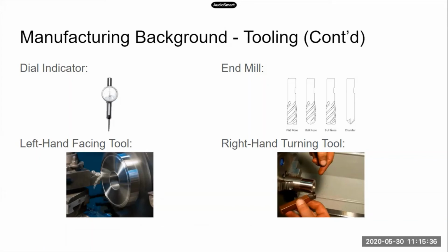So you can do that with an end mill, which you would not be able to do with a drill. So it basically is how you use that bottom portion. Ball nose has more of a curved edge, so if you need more of an inner radius there, that's nice. More of a contour.